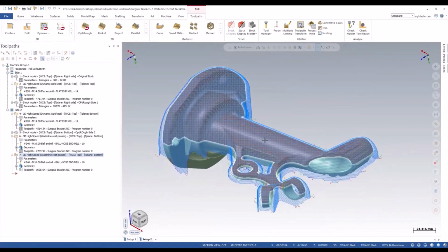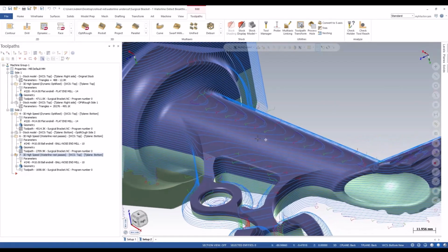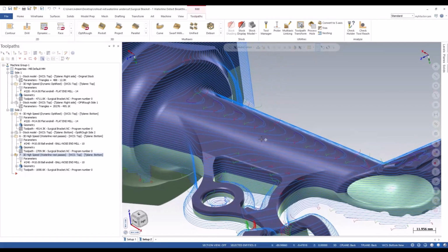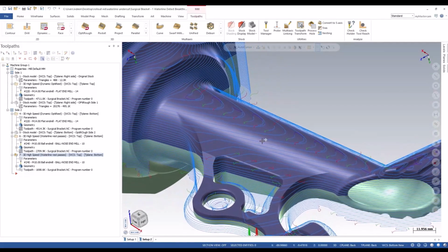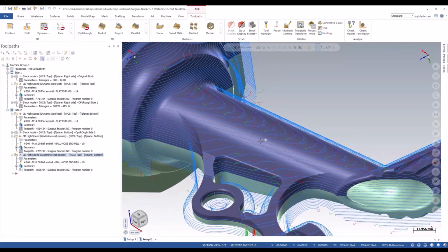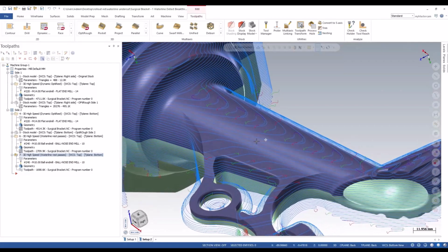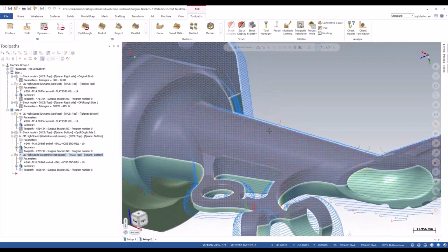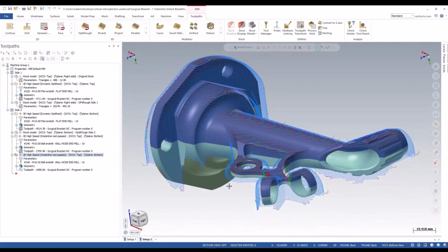First thing we'll look at is the top of the part. You see those little short single passes, or in some cases it even does a double pass. So in between each of those very small step downs, it does additional passes, cleaning up those scallops and giving us a better finish only in the areas that are shallow, so you don't have to really ramp down the step down globally and take a lot of extra time.